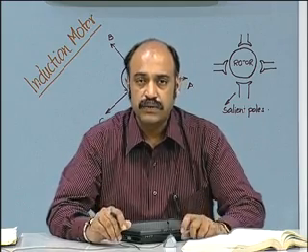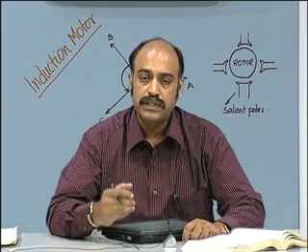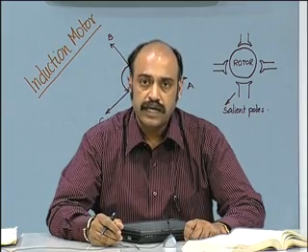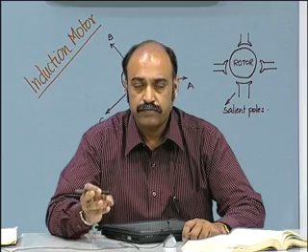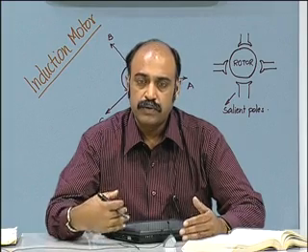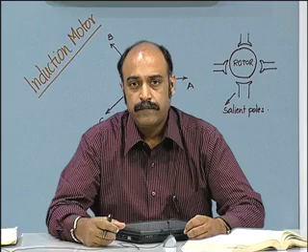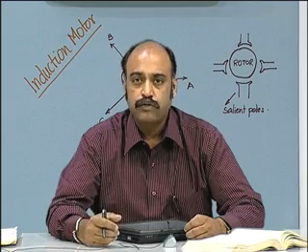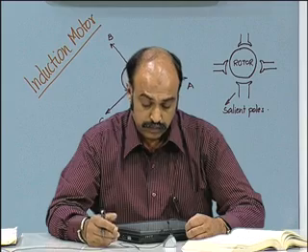Otherwise, the equivalent circuit is just the same as in the case of the transformer. We saw the phasor diagram, and also from the phasor diagram and from the equivalent circuit, we were able to list down the various equations for the active power flow and the reactive power flow components of the induction motor.